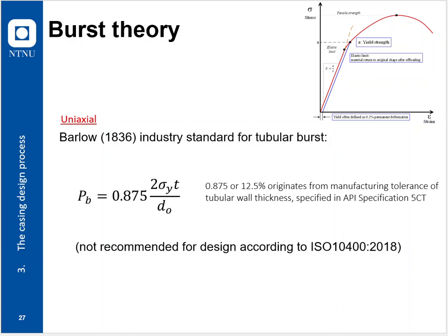And if you take a slightly deeper dive into things, you will see that the standards that are governing how to calculate the loading tolerance for pipe, the ISO 10400 or API 5C3, you will find that they are saying be extremely careful with this formula. And that's a little bit academic.